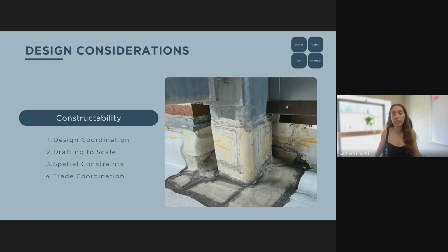So that's number 3. So I'm going to go back to this photo that gives me nightmares. Did we consider if the space was accessible for the required installation method? Likely not, because again, somebody pulled that short straw of getting to roof in that nook and cranny. A similar common example, let's say the structural engineer is installing dunnage to go on the roof, coordinate this with the architect or the designer of record for the roof assembly to know what the height is. So that dunnage is going to be installed first, and you've got to be able to fit a person under to install the roof assembly. So how small do you think your roofer is?